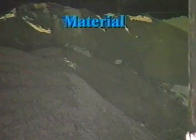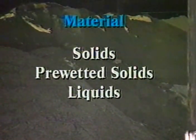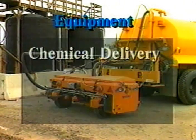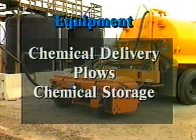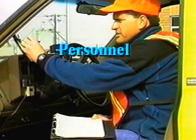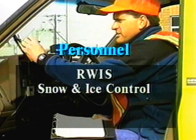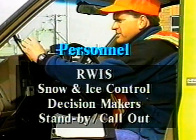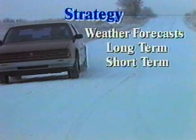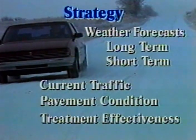Many tools are available to the maintenance manager for anti-icing. Tools for operations include the solid, pre-wetted solid, and liquid chemicals necessary for preventing the ice pavement bond, equipment for delivering the chemicals at appropriate rates, plows with effective cutting edges, and chemical preparation and storage facilities. Personnel tools are the people skilled in the use of road weather information systems, snow and ice control equipment, technology for decision-making, and personnel standby and call-out procedures. Decision tools include long to short-term weather forecasts, real-time data on traffic, pavement condition, and treatment effectiveness.